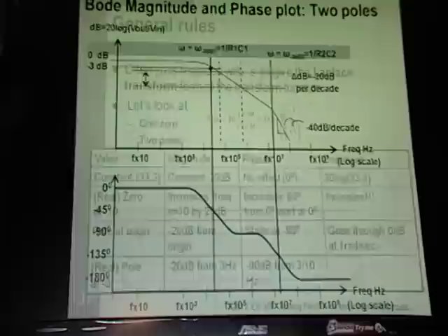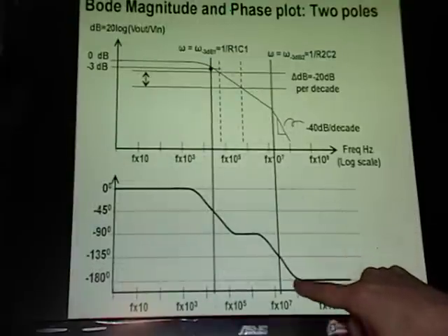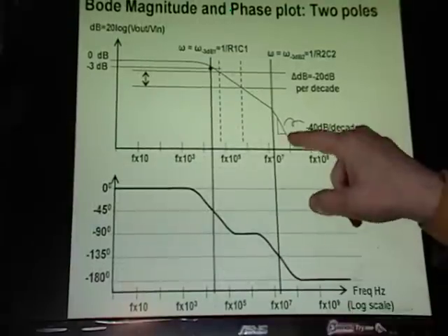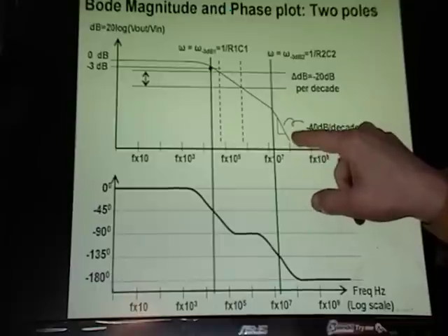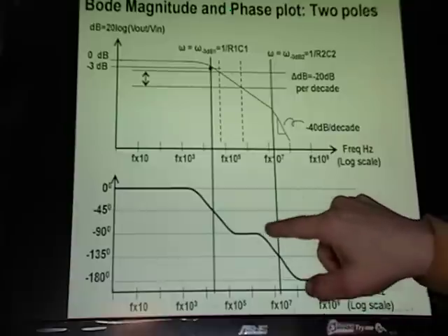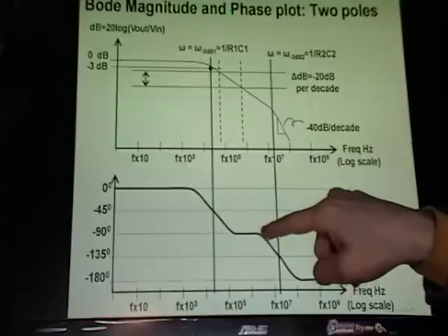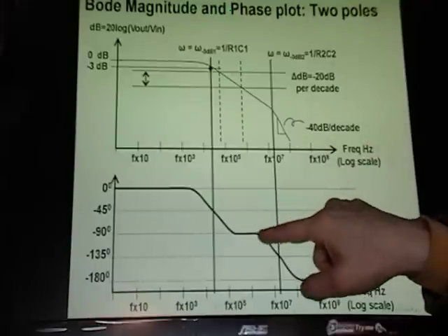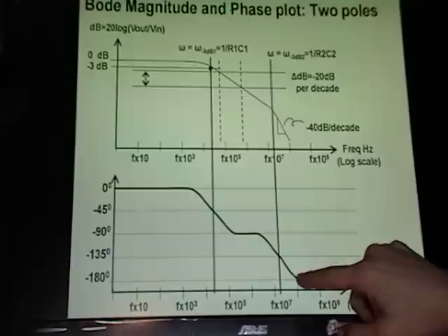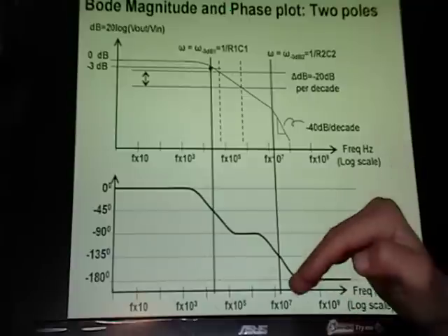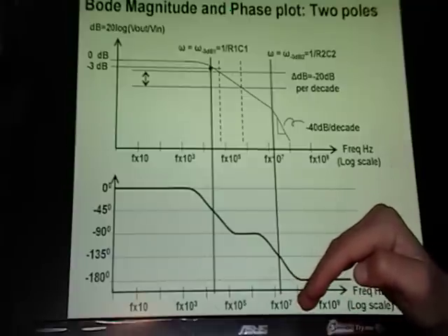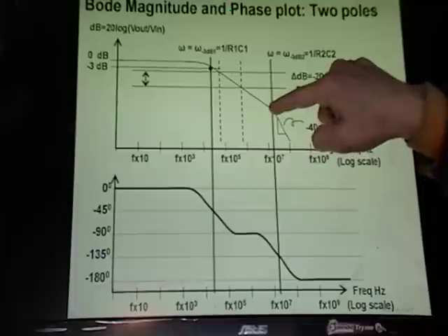Remember on our plot over here, if we drop to 180 degrees, we want our amplitude to be less than 1, our gain to be less than 1. If you have a right-hand plane 0, as I remember it, so I have to check, the phase continues dropping, so it continues towards 180 degree phase shift, but it flattens this out.